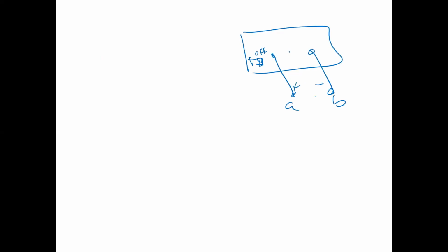Whatever is in there, it'll tell you the Thevenin resistance of that thing. Just take the voltage that you end up getting at those terminals, divide by 1 amp.